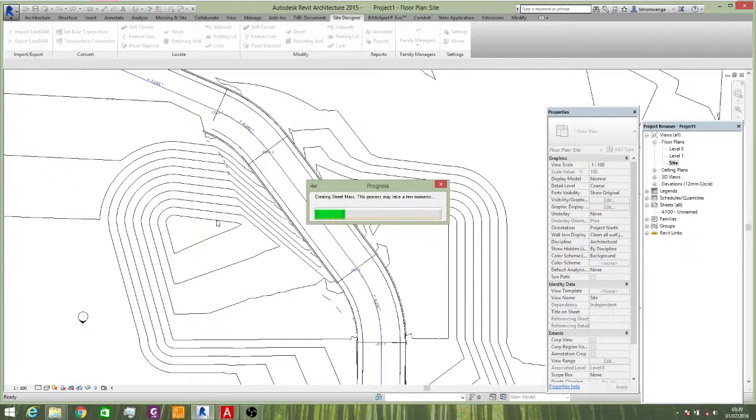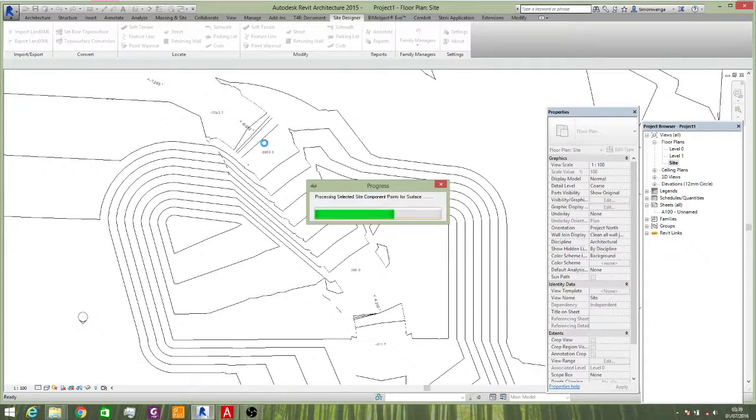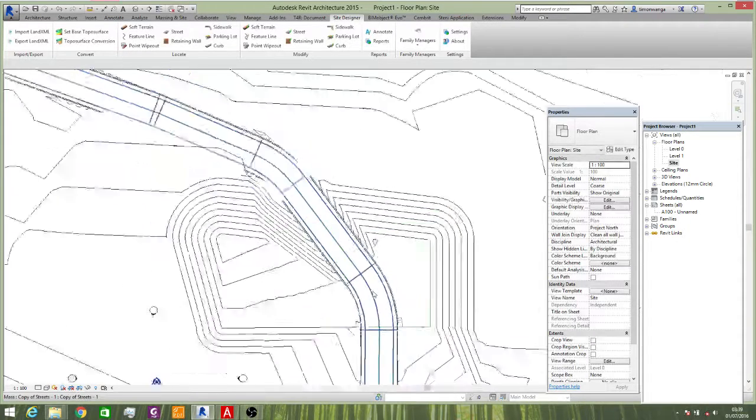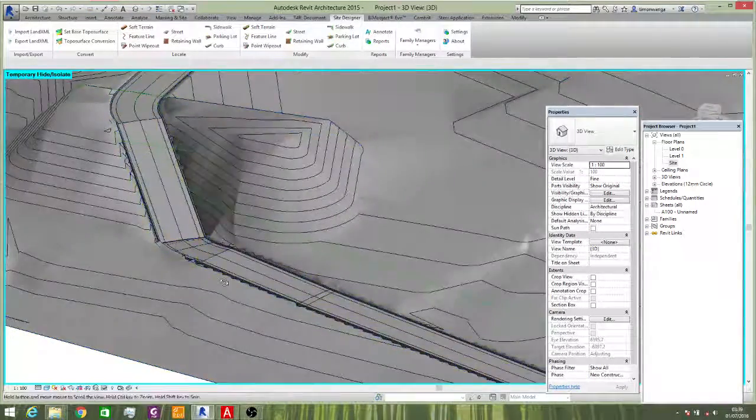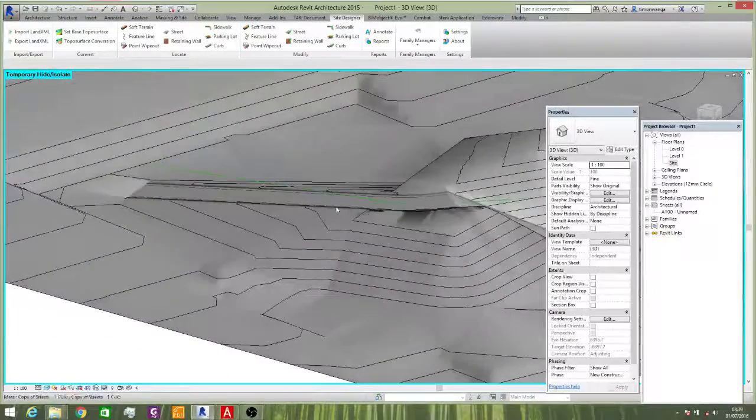It creates the mass grades for you, and you have your road. While it's doing that, it's important to know that you can actually create more than one road, or even intersecting roads, but the complexity is such that at the point of intersection, the reference line or the reference sketch line should only be a straight line. Now if you intersect a road at such a curve, then Revit Site Design won't accept it, and that's another disadvantage. Not as such, but it's realistic.